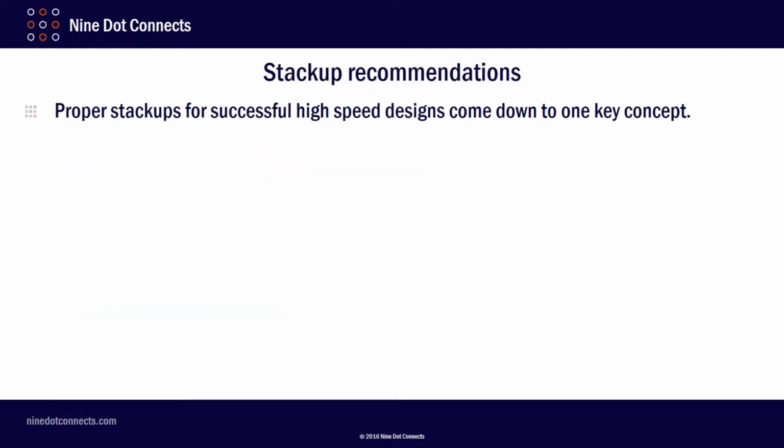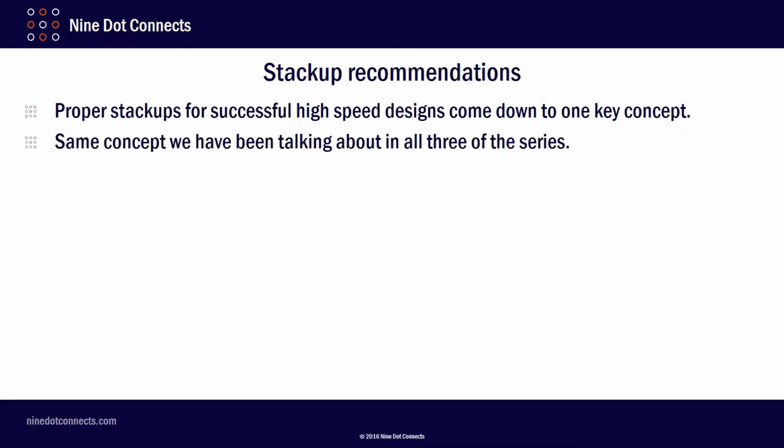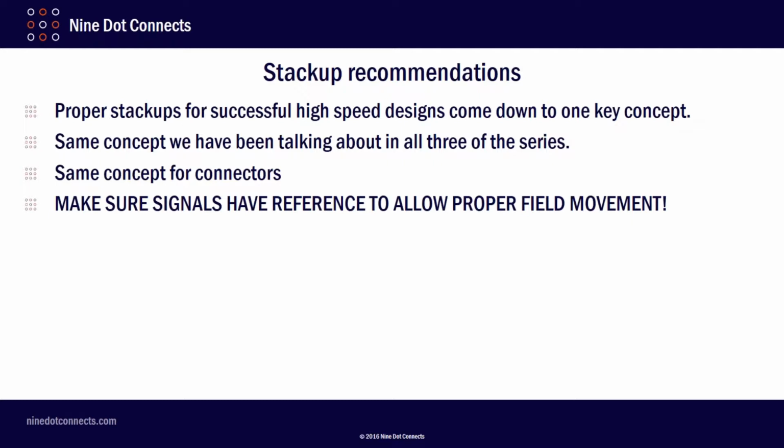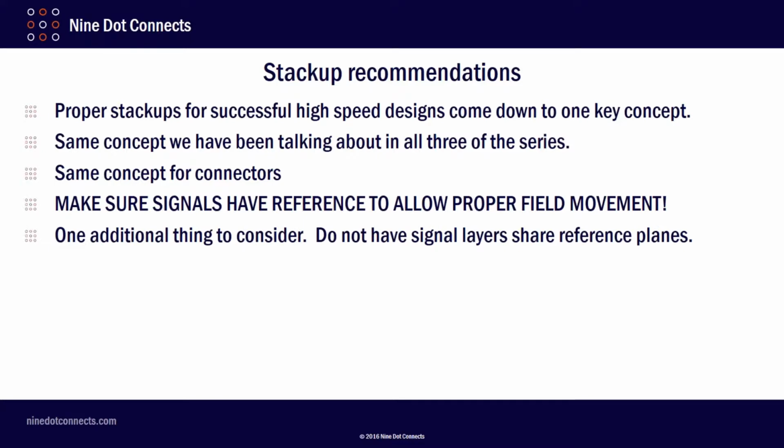Now, stack-up recommendations. This is another very common question we get: what is a good stack-up? In my opinion, good high-speed design stack-ups come down to one key concept. It's the same concept we've been talking about in all three of the series. It's the same concept for connectors. Make sure your signals have reference to allow proper field movement. Whether it's a ground or power plane, you need to make sure you have that reference. One additional thing to consider: don't have your signal layers share reference planes, if at all possible.